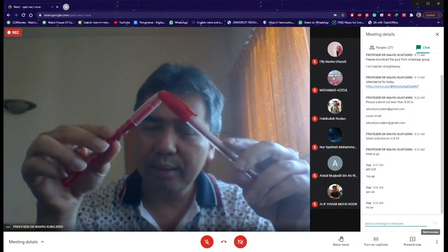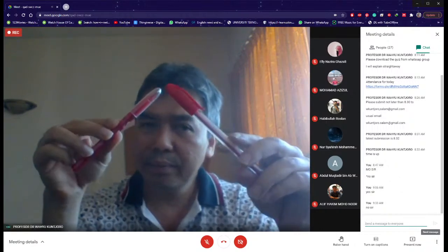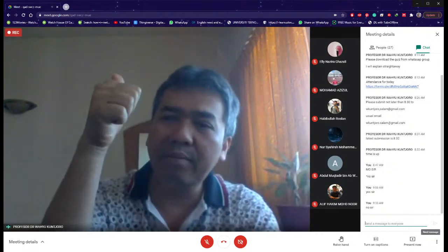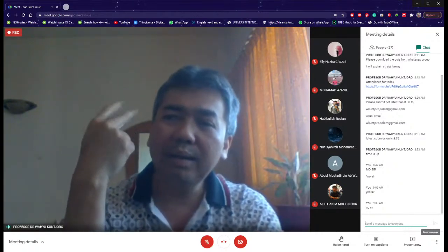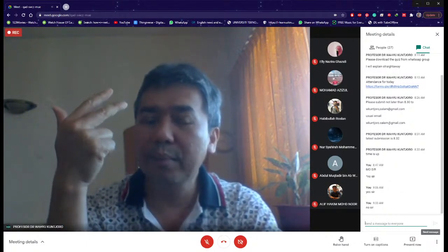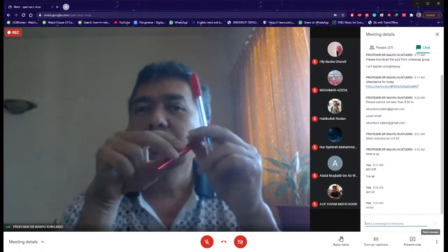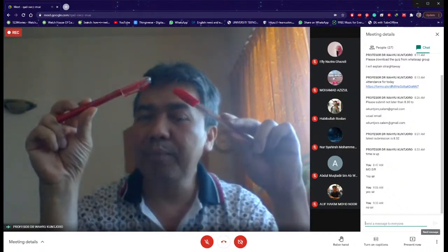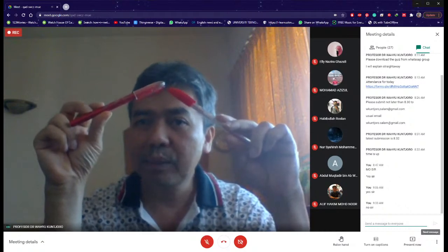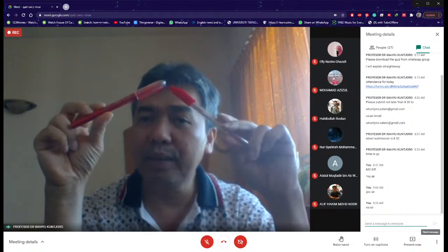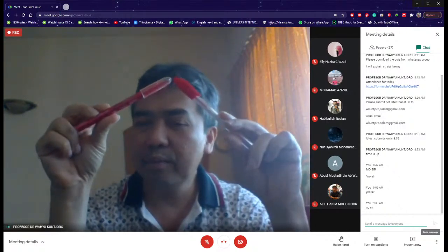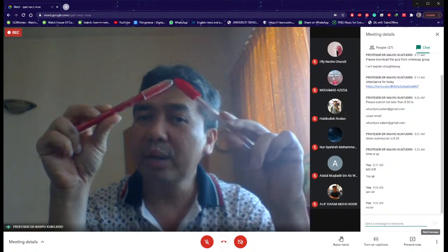So you see here, we have difference of connection. You do either by welding, or by pin joint. If you do by pin joint, then you will have truss. If you do by welding, then you are going to have frame.